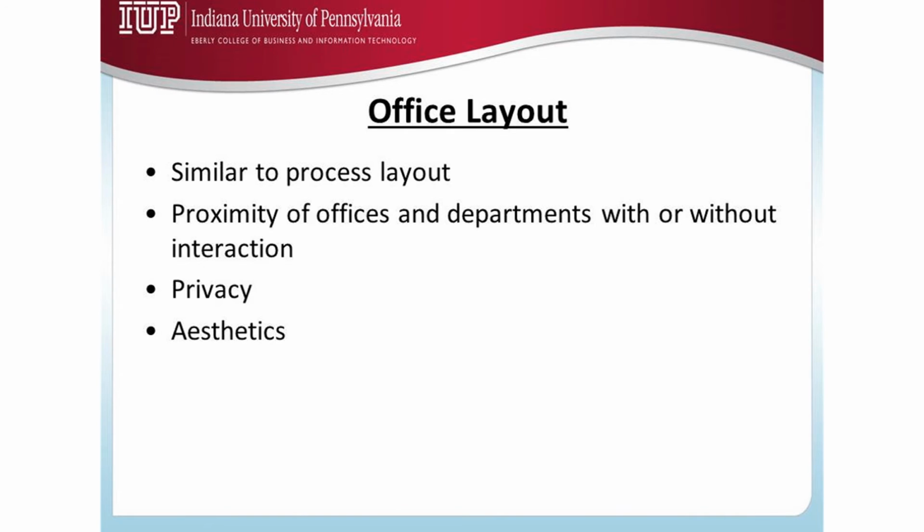An office layout. An office layout is very similar to what we discussed in process layout. If you recall, the job shop, there also we used a from-to chart and a Muther's grid, or the relationship chart. Here also we do the same thing. How many times do we have communication between different offices, movement between different offices? We need to know that. And what is the relationship between different offices?